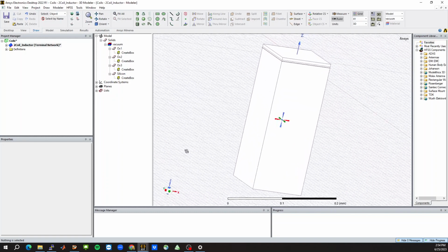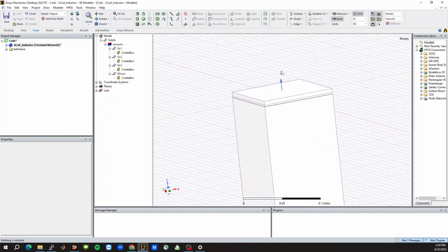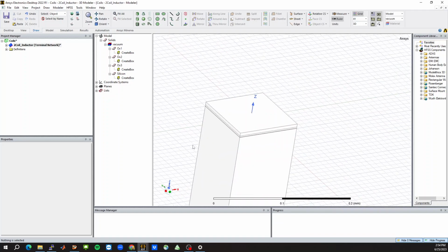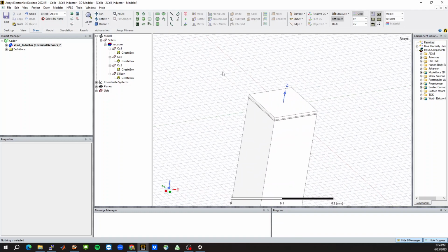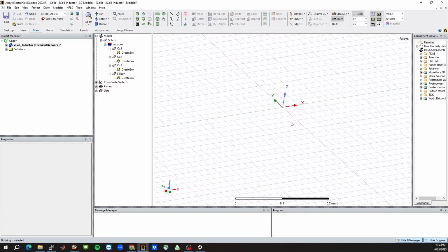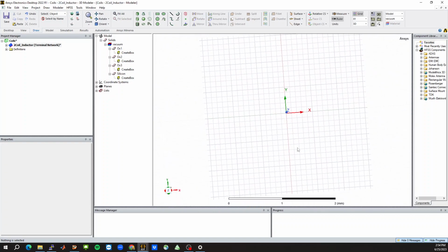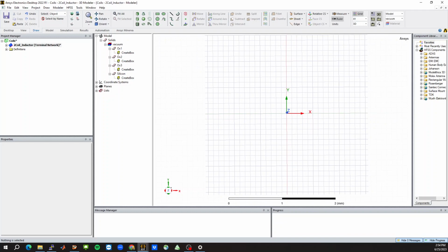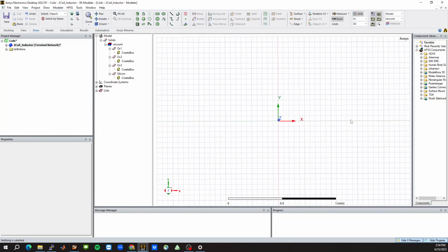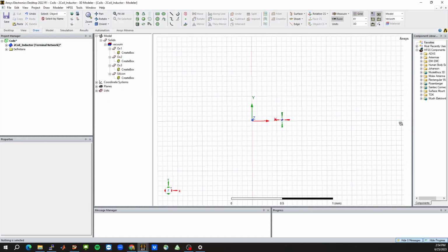Typically, you may also have a nitride layer, which you want to include in case the inductor doesn't have any ground plane underneath it or any shielding. So let's just hide these layers, and then now we can start with the more interesting part, which is drawing the actual inductor. Okay, so since we want to make it parametric, it's not very straightforward, but I've done some simple geometry calculations to make it much easier.